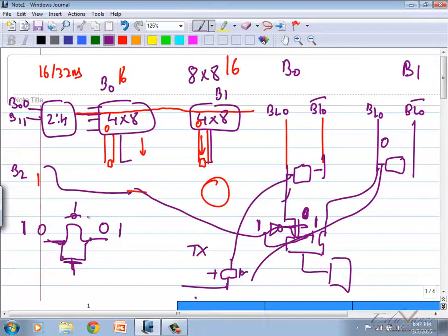Yes or no? How do we write? First precharge, correct? Wait for that node to come up. Then depending on whatever data, sense enable 1 has to be done, otherwise it will not let the data go out. Correct? Yes or no? Then comes your write enable.